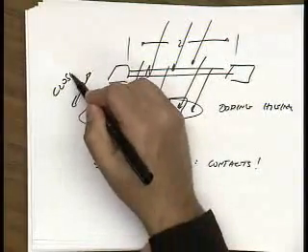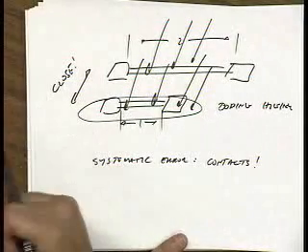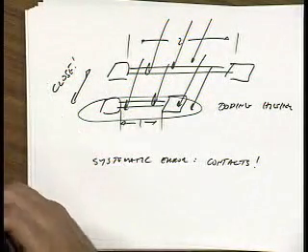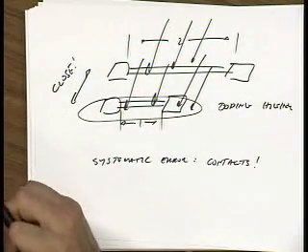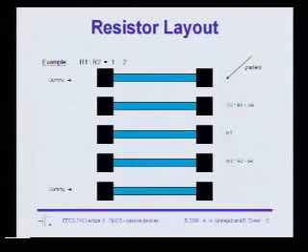And the idea is that even though these are very close together, so you make these close, so the doping variation is very small, you still will see some variation. And in fact, if we had been a little bit more clever about the layout, we could avoid that. So again, let's go back to the slide and see how you do that. So what I'm going to do here is I'm going to lay out my device with 3 unit elements. For the moment, let's ignore these dummies. So then I could just connect one like this, right? And then I could have one resistor here.